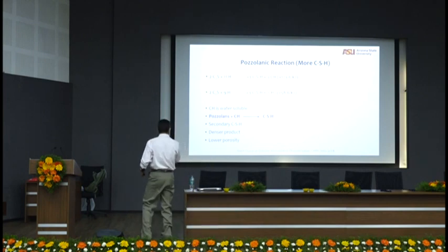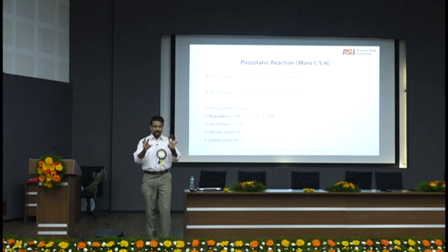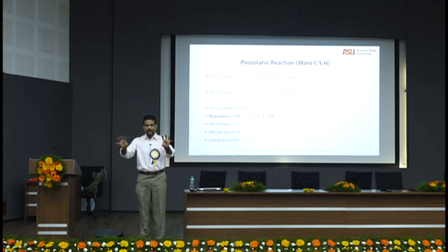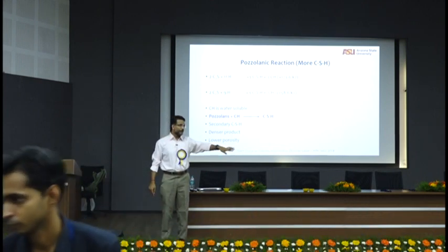See, I know there's no whiteboard. Okay. So think about a cement particle. So this is competition for reaction. Think about a cement particle, think about a fly ash particle, okay? This cement particle reacted from the surface, like we were talking about, formed CSH and calcium hydroxide. This fly ash ate up the calcium hydroxide, reacted, formed CSH, right? But there is still residual solution. That solution diffuses through the initial cement particle, goes a little more in, produces more CSH, and then more CH also comes in. Some other fly ash does it. So until the cement gets hydrated completely, your calcium hydroxide is not going to go away.